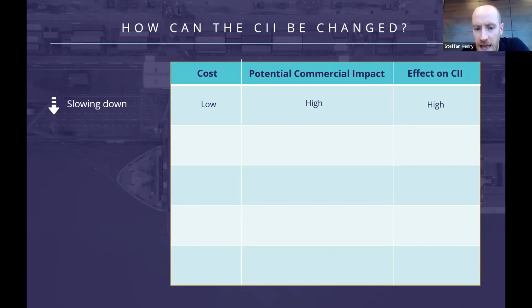If the vessel has an engine power limiter fitted to comply with EEXI regulations, it's quite likely that this forced reduction in speed will also have a positive impact on the attained CII, but it does depend on the average speed the vessel travels at anyway, and how the vessel operates based on its voyages and so on.